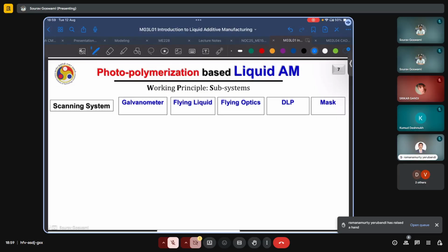And we use the combination of these two mirrors to scan or shine the laser light all over the print area. Now the galvanometer mirrors are very light, and because of being light, they have very low inertia. So they can be scanned at very high speeds over the entire printing region and can be used to cover the region of interest.